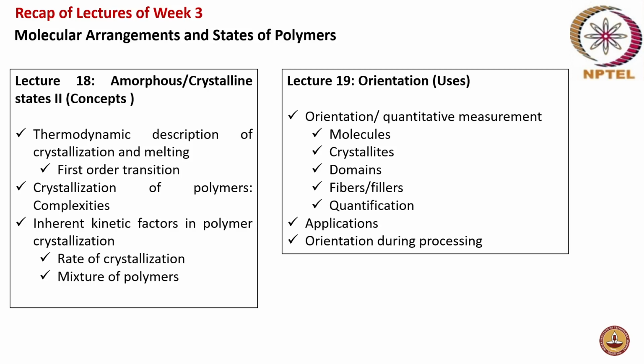Like in biaxially oriented films, for example, in BOPP, right? Where the properties actually differ in different directions, correct? Because of the orientation, right? Because of the stretching in both the directions, biaxially oriented, no? Stretching in both the directions, so your properties also vary, correct? And then ultra high molecular weight polyethylene. So we could see that the tensile strength goes up to 3000 megapascals in ultra high molecular weight polyethylene because of the orientation, which is comparable to aramid, graphite,